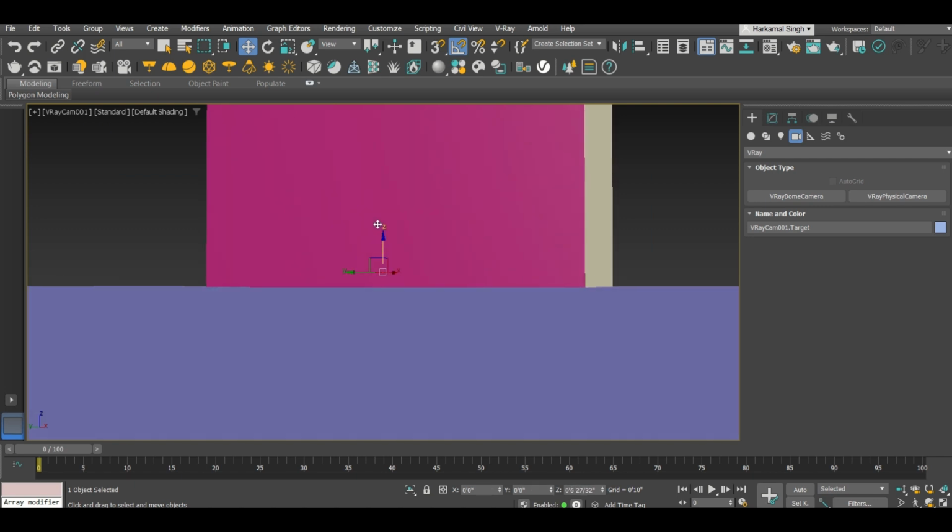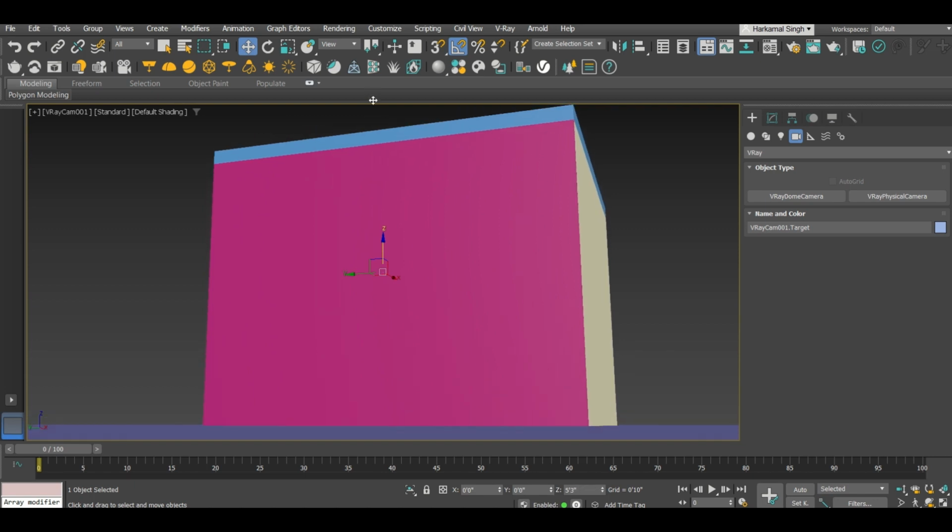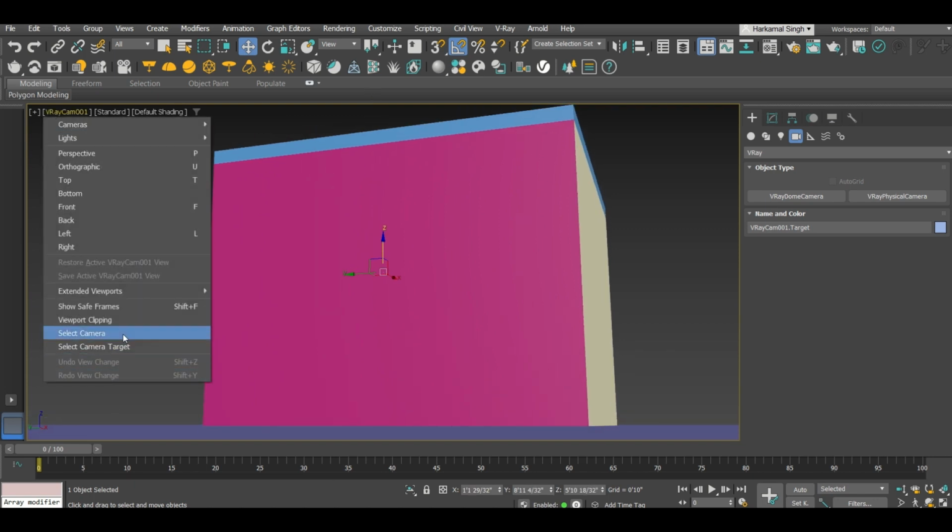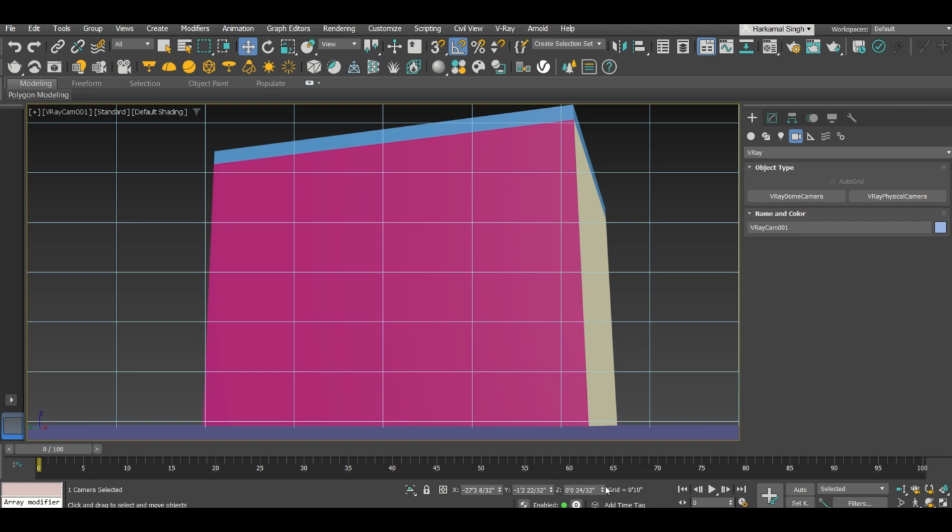This arrow key option, you can change by W E R. Three buttons are there, very easy. In one of the previous videos, on basic settings of modeling, I have explained this. By pressing W, you will be in the move command. Pressing E, there will be a rotate command. Pressing R, there will be a scale command. So we are in this one. Once this is selected, I can change the view. Again, I'm doing some normal settings, selecting the camera, giving some more height to the camera.